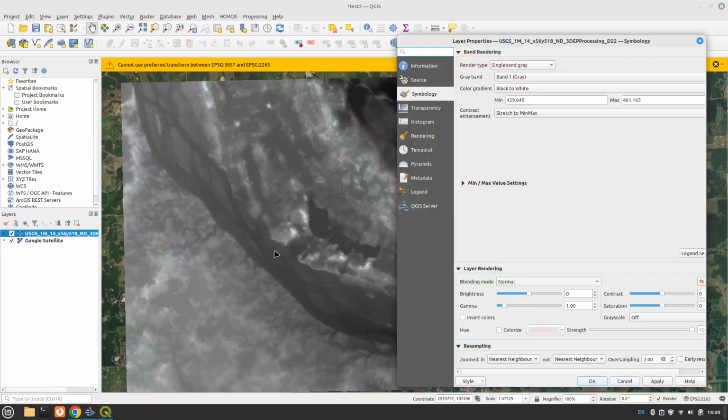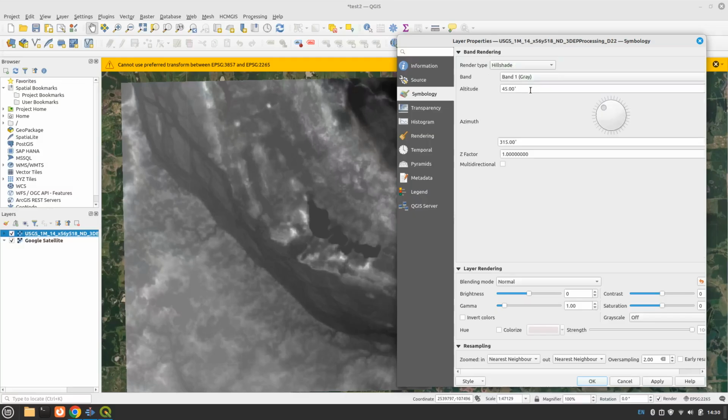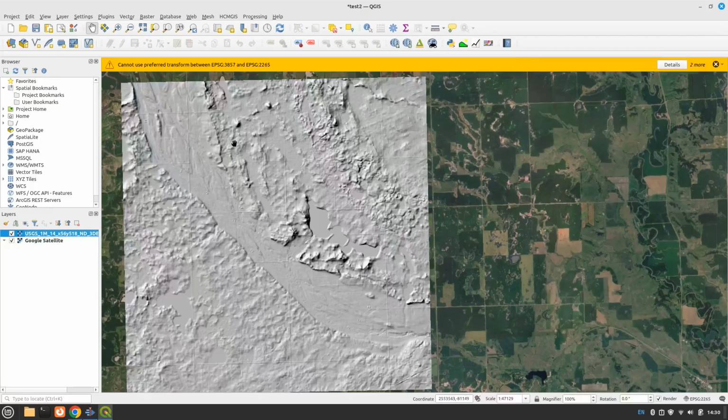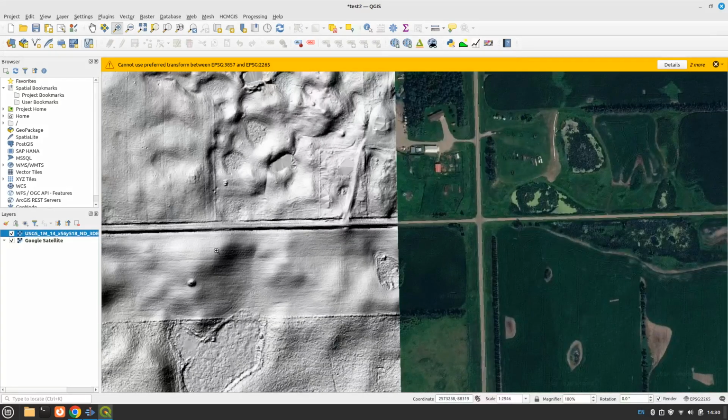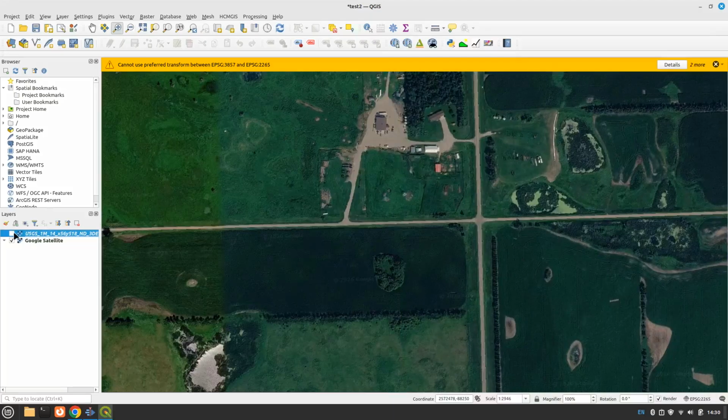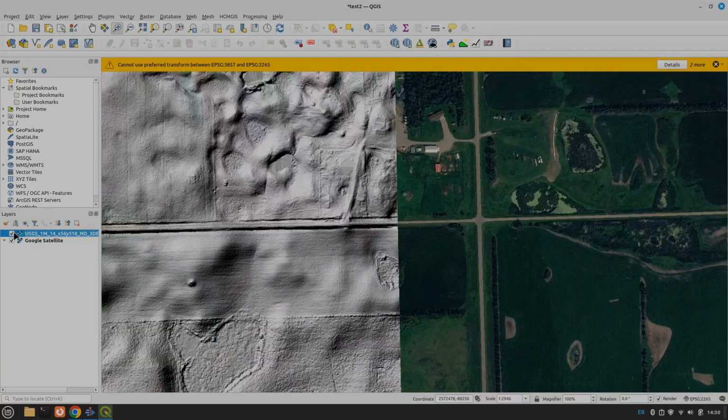I've given an English and American example on this video, but it's the same process for any country. Find the LiDAR data source, download the DEM and import it as a layer. Just be aware the terminology around LiDAR data is not consistent between websites. Some call it LiDAR data, others call it DEM. You will have to play around if you're looking in other countries and see what data is available.